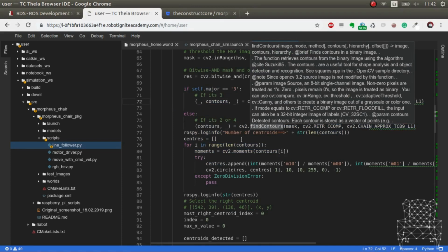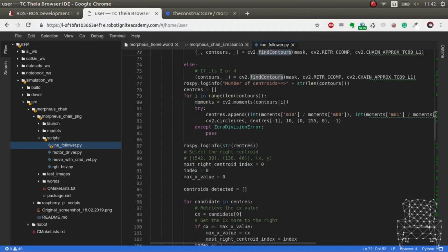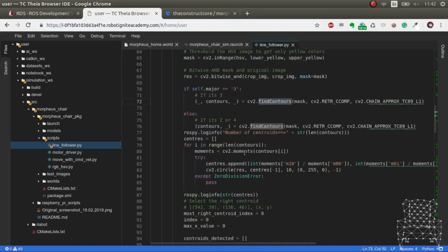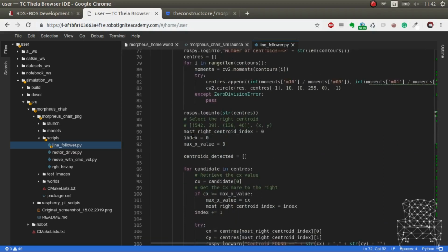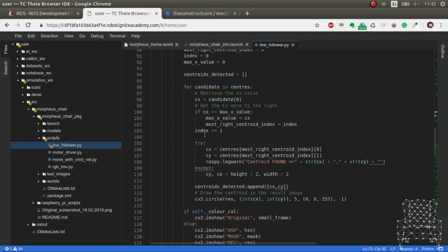And from there, we extract the centroids, which basically are blobs of colors, and we generate where we think the most quantity of white is, if there is one blob or various blobs. Again, it's a very deep subject, but basically here we're detecting where the line is.